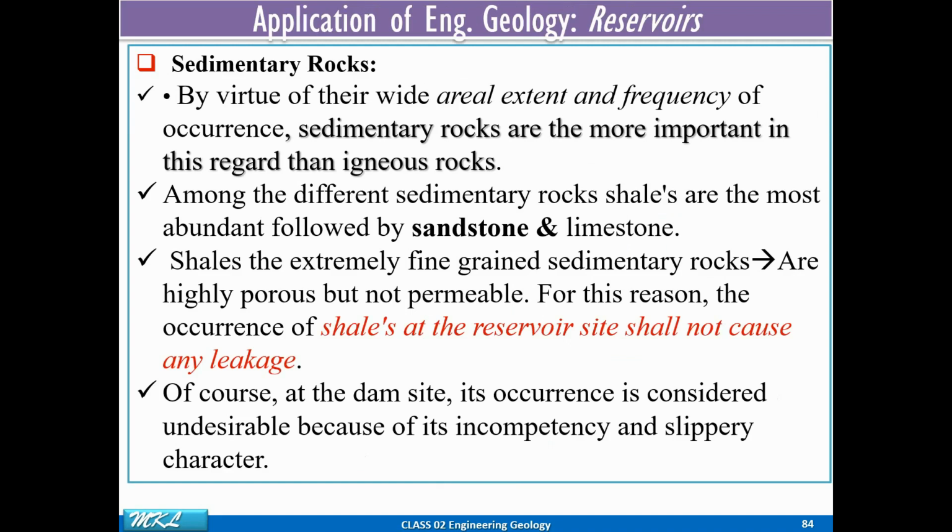So in case of sedimentary rocks, now you can say sedimentary rocks are porous and permeable. In general, by virtue of the sedimentary rocks, I will not consider it as a reservoir. I don't want to see the sedimentary rock in the reservoir site. But few sedimentary rocks are more abundant, like sandstone and limestone, and one is the shale. Shale is not good for dam construction because it has a slippery base.